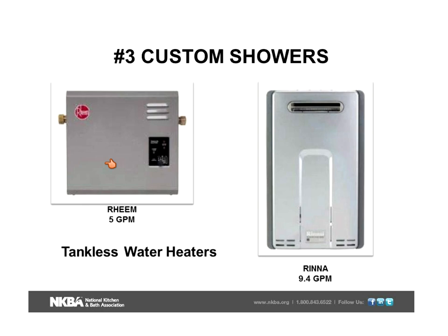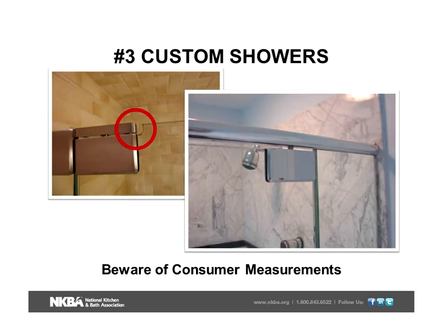Now, of course, a little flex built into it, I'm sure. What's the chance that 2 people are going to be taking a shower at exactly the same time? Now, remember, there's no stored water here, so we're kind of pushing it to the limit. You add a body spray, and this will not work at that point. And generally, we're not going to add 1 body spray. So we may need to think about the size of that on-demand or tankless water heater.